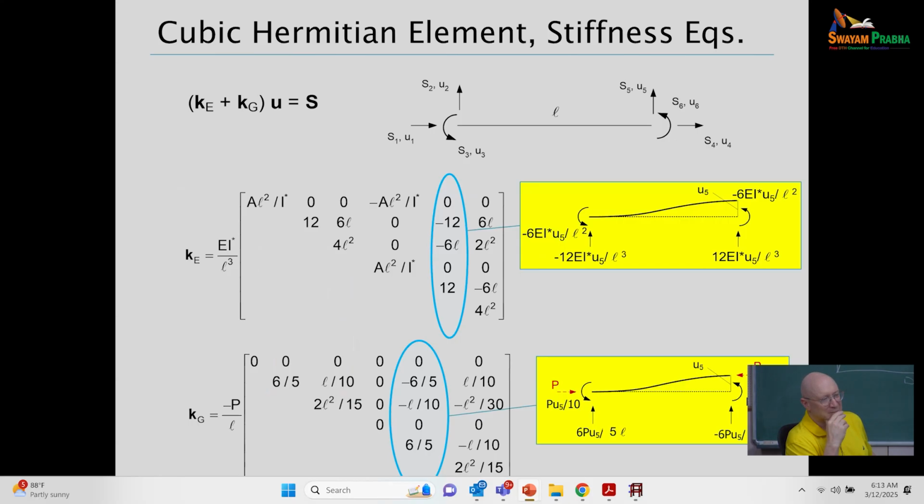Since it's a cubic, it's capturing the bending relative to the chord, so then you're getting some representation of the P small delta. But again, the internal loads like UDL and all, it will be approximate, not correct, right? Yeah, if you've got element loads on the interior, now there's other things going on.